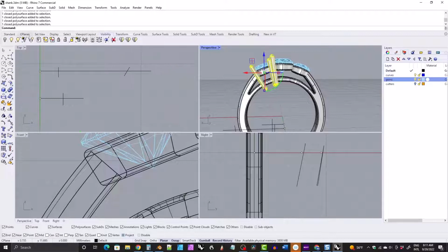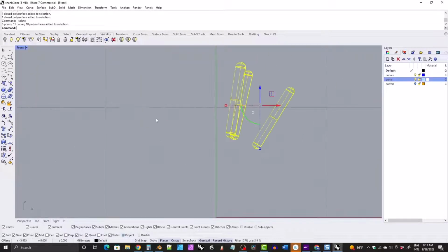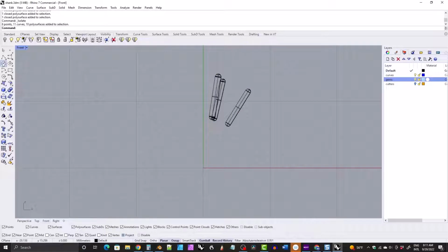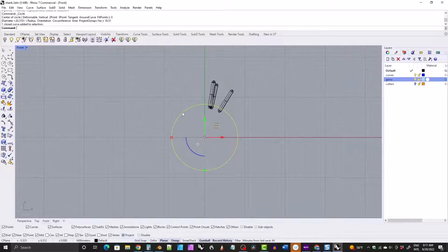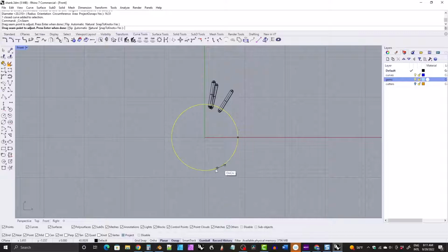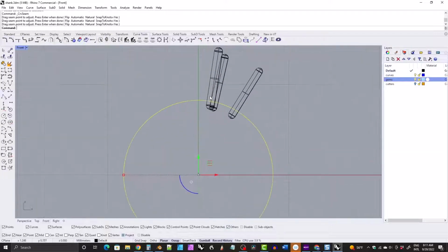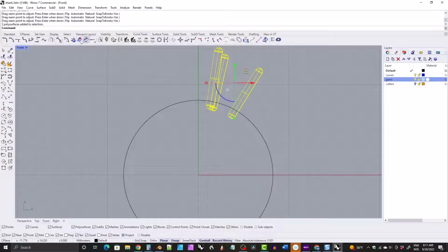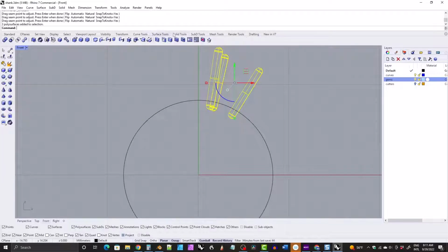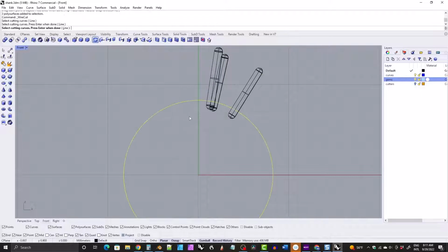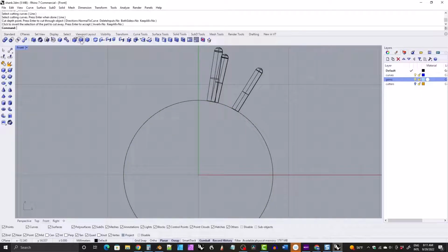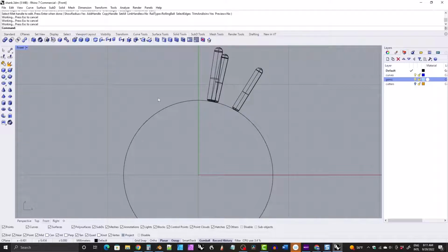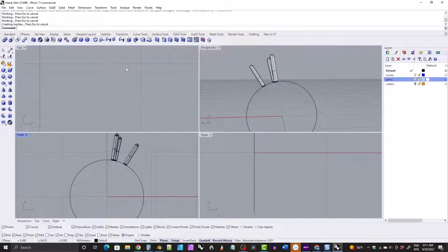We'll come into the front view and lay in a sizing circle again. We lose our sizing circle every time we make that shank. So I'm going to lay in another sizing circle, and remember to pull the curve seam down to the bottom. We'll select these prongs and, from the front view, use wire cut to trim the bottoms of the prongs off. And then we'll fillet the bottoms by 0.15 or 0.1, something like that. Okay, we'll bring everything back real quick.